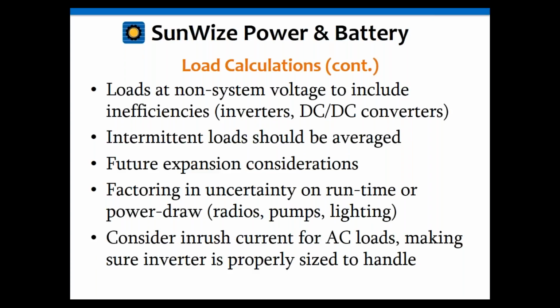Generally for inrush on AC loads, you need to size your inverters and equipment for that. But it doesn't usually come into account because it's so brief. It's only for usually a few seconds. It doesn't come into account for your sizing. It's only important to make certain that your power equipment can handle it, but the system sizing doesn't really care, again, because it's only going to be for a few seconds for inrush currents.